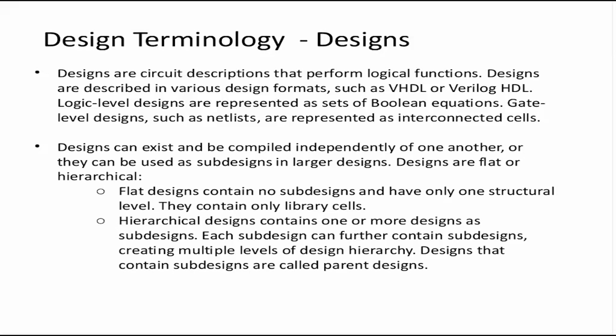Designs can exist and be compiled independently of one another, or they can be subdesigns in a larger design. By that definition, designs are either flat or hierarchical. Flat designs do not contain any subdesign. They have only one structural level. However, they may contain library cells. For example, a simple design like a full adder or a half adder will contain a list of library cells if it's a netlist, for example AND gate or OR gate, but inside it does not contain any other design. So that is a flat design.